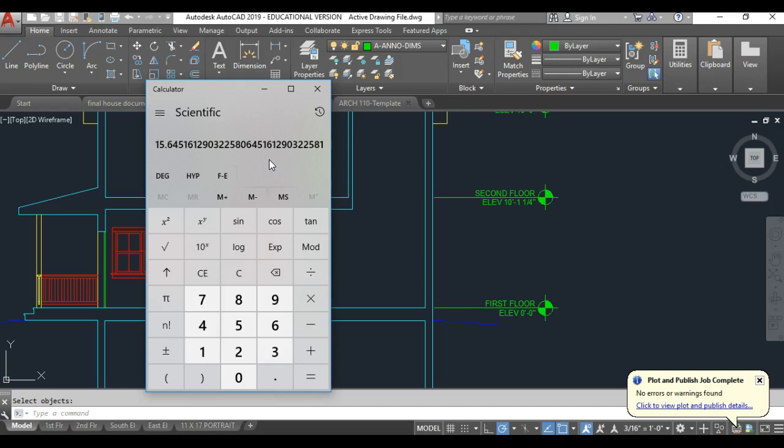I don't know what the number is, and we can look it up when we're done drawing. I don't need to know. I'm not going to calculate anymore. I just know that I need 16. I need to break this floor to floor height up into 16 different pieces, and then the result is going to be less than that 7 3/4, so I'll be within code.